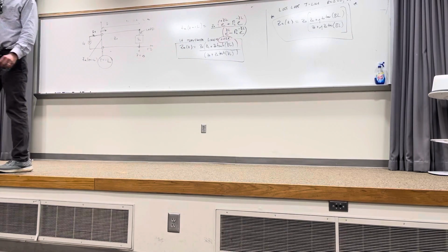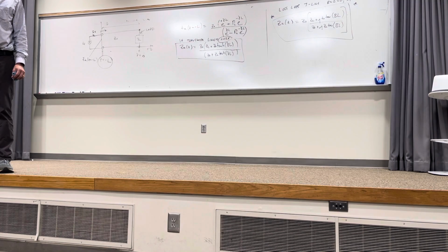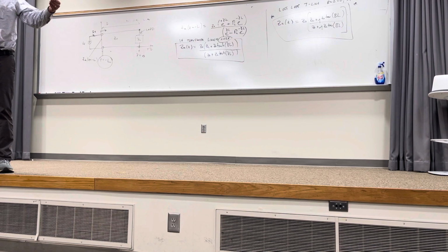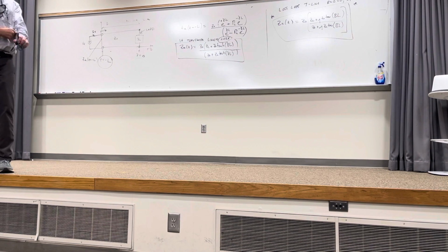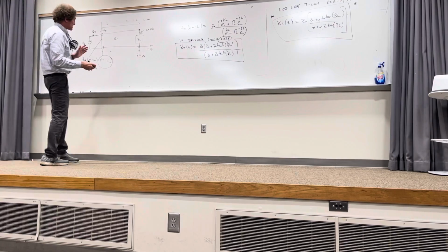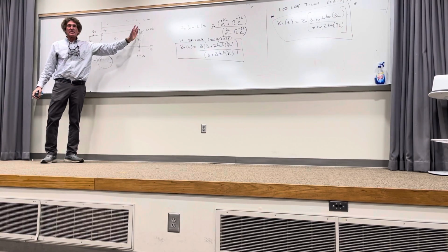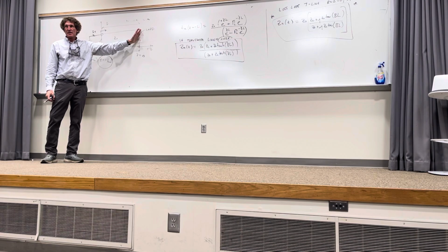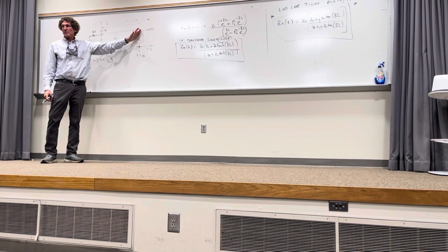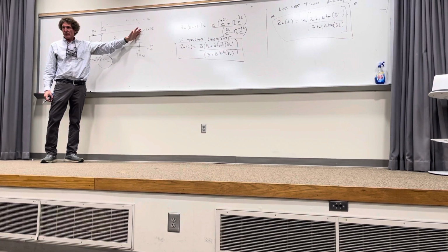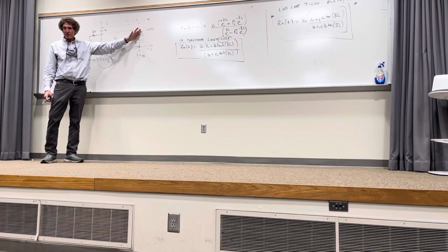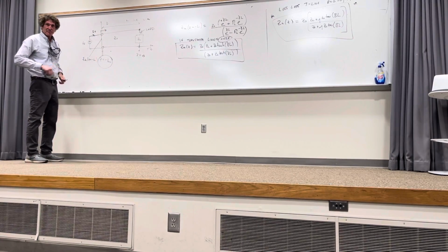Are you good with that, everyone? Okay. I try to work more examples, but I have to get this theory out. So that's the input impedance to this line. There is an assumption. Does anybody remember the assumption about the length of the line and wavelength? How long does it have to be before it actually looks like a transmission line and waves are developed? It has to be 1/10 of a wavelength or longer, right? Just remember that, at least 1/10 of a wavelength, or else it's just a couple of wires connecting this.